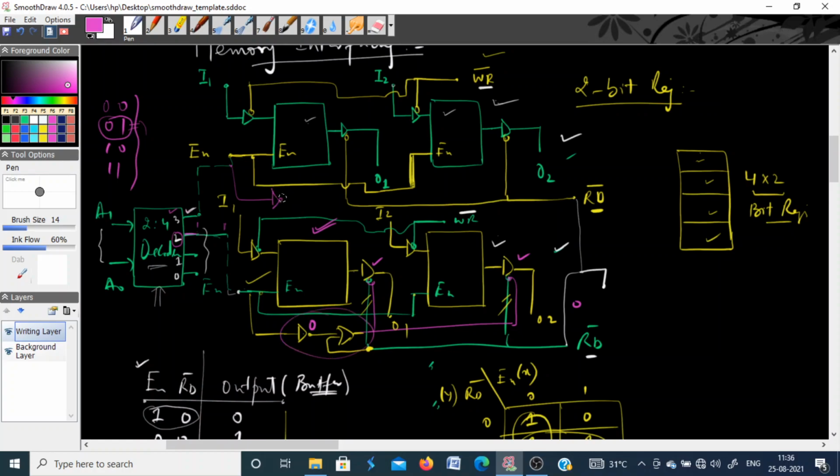Okay, so you have an inverter circuit here, and then it has to be combined with this read signal again using an OR operation. This has to be connected with this. Okay, so if it is 0 here and 0 comes from the read signal, so 0, this will give you 1, so 1 plus 0, it will give you 1. It means this buffer will not be activated.